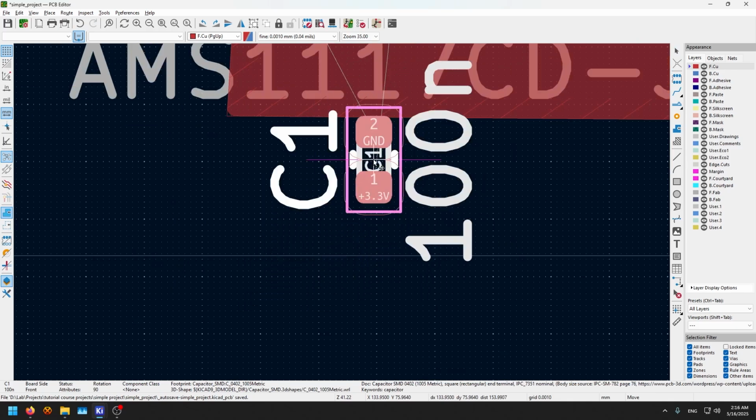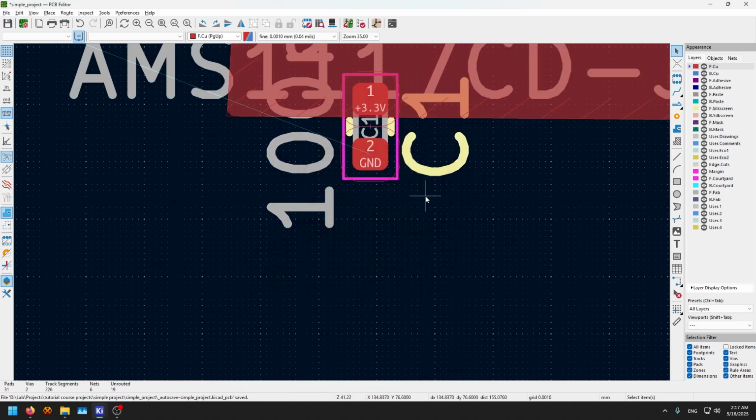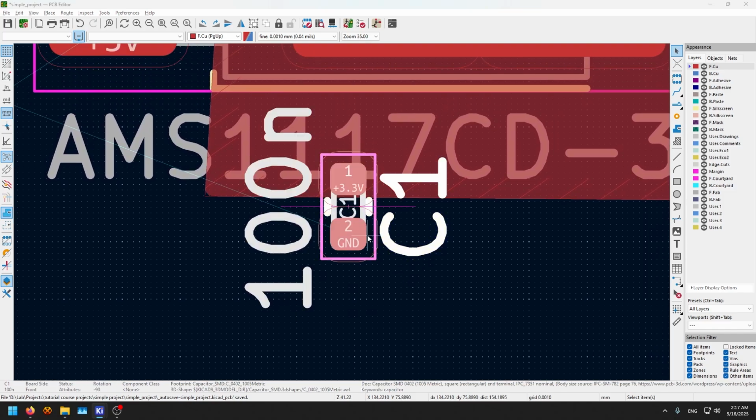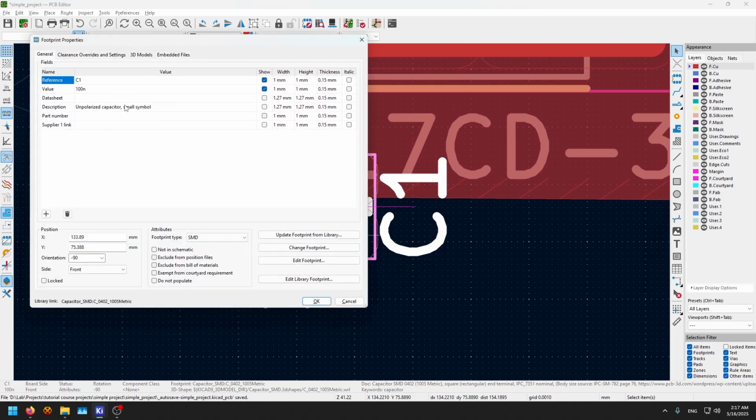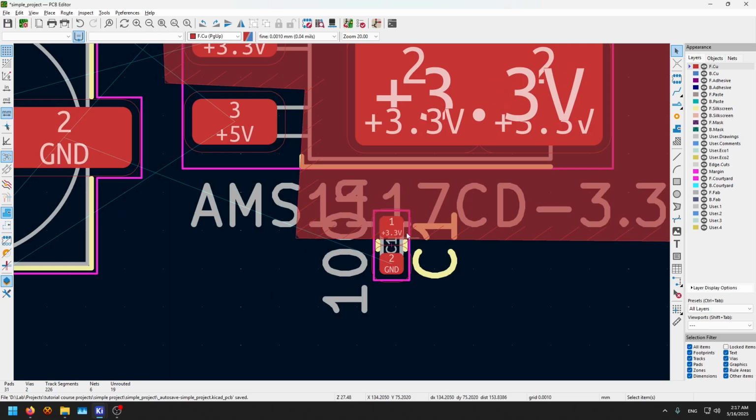let's move this in here, which is 3.3. Pour again, and it's fine. This is an 0402 resistor. Maybe due to the amount of the solder in here and the big plane, maybe this thing doesn't get to be soldered correctly because of using a solid pour.